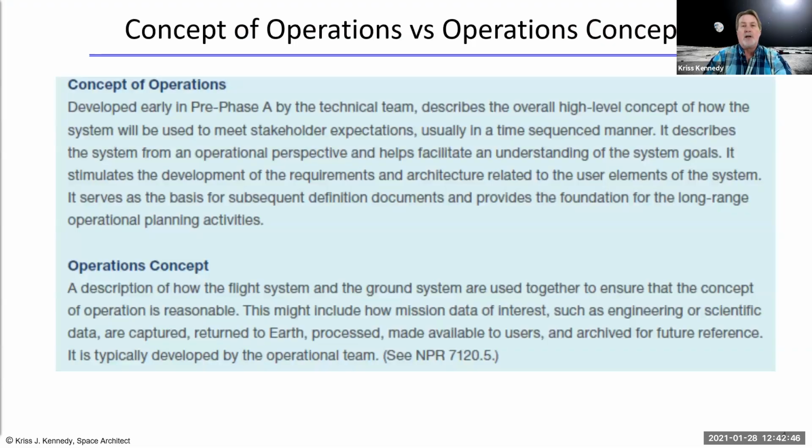So, concept of operations versus operations concept. They're often used interchangeably, but they're not the same in space system design or at NASA. Concept of operations is developed early in pre-phase A concept studies by the technical team. It describes the overall high-level concept of how the system will be used to meet stakeholders' expectations, usually in a time sequence manner. It describes the system from an operational perspective and helps facilitate an understanding of the system goals.